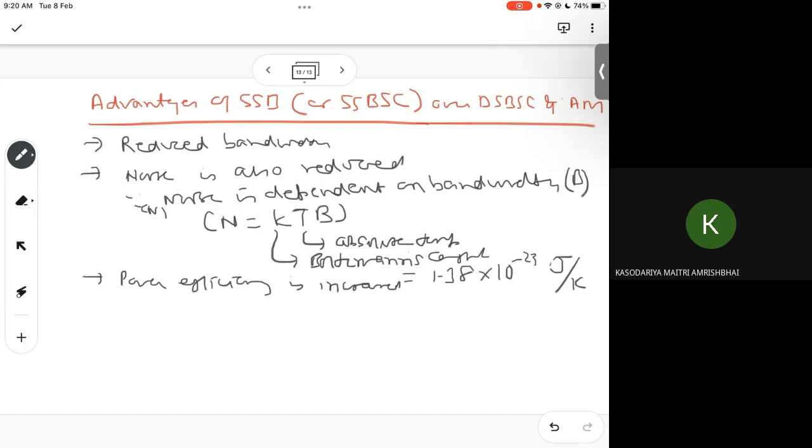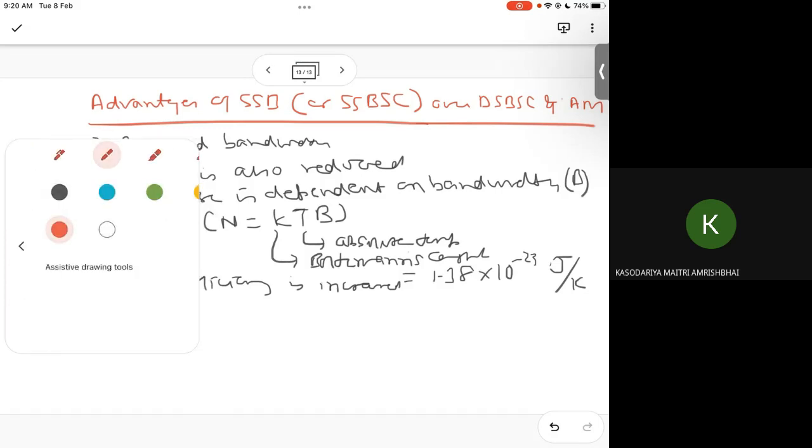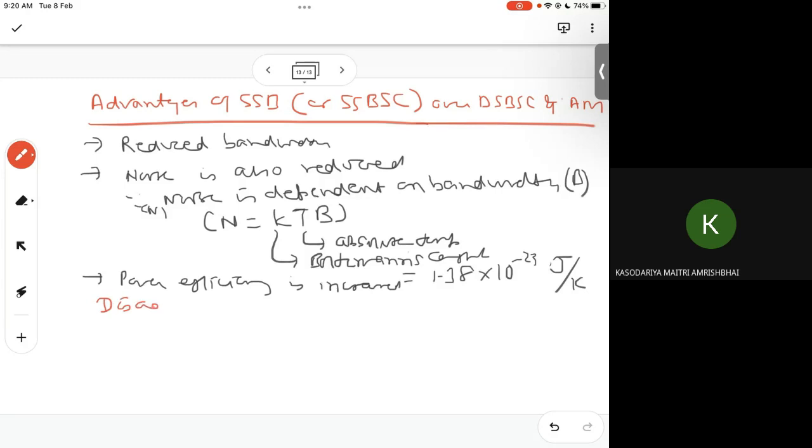But obviously, when we do such a thing, we have to suppress the carrier and also suppress one of the sidebands. For suppression, we need additional circuitry. So the disadvantage is again complex circuitry, because now you have to suppress two things. You need to suppress the carrier, which was earlier a disadvantage for the double sideband suppressed carrier, but in addition to that, now you have to suppress one of the side frequencies. So this is what we call the single sideband suppressed carrier.